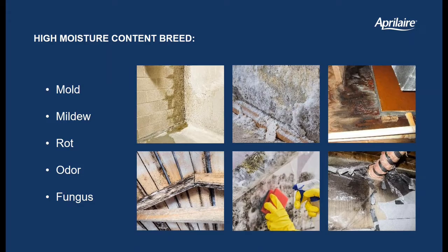We're trying to reduce mold and mildew. These things, of course, are a health concern, but they also can cause structural damage. So these pictures show quite a bit of mold and mildew growth. I just want to point out that if you can see a lot of mold coming through your drywall, remember, mold likes to grow in the dark. So it's growing inside that wall cavity, and it's just coming through the wall. You'll see mold colonies on the exterior of the drywall, but it's also growing behind that wall quite aggressively.